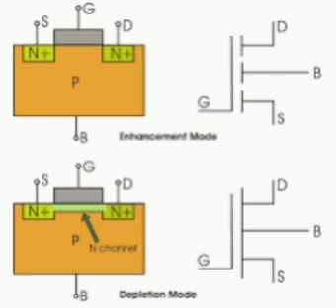LCD, liquid crystal display. Operating principle is dynamic scattering of light. Power dissipation is of the order of microwatts. Response time is in milliseconds. Operating life is 50,000 plus hours. It is used as a display device. Material used is liquid crystal that is activated by electric current.